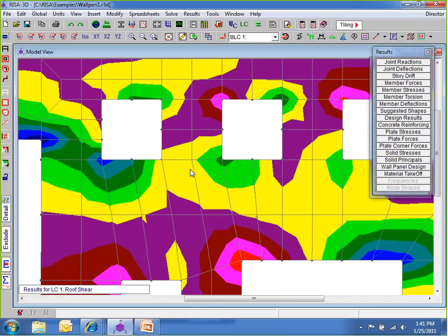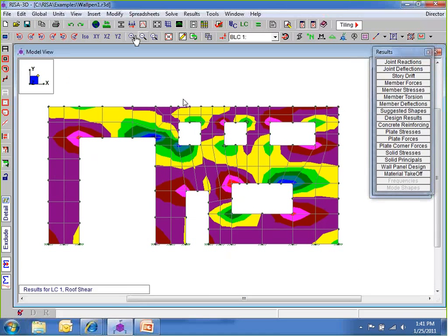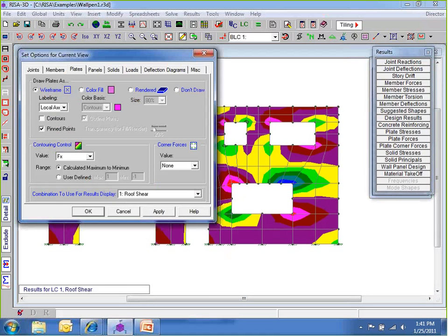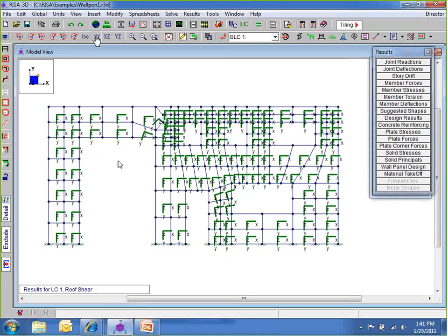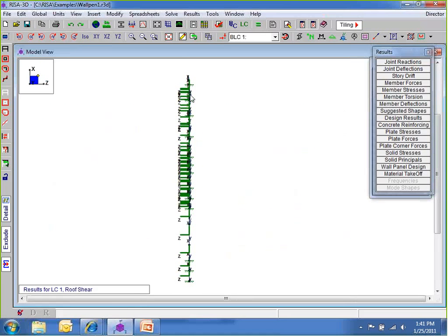So really, once you draw your plate model, just take a quick perusal. Say to yourself, okay, how does this look? The best way I always do it is just turn my model on its side. If I see any of the local axes pointing in the wrong way, I can go directly to that one and take a look.